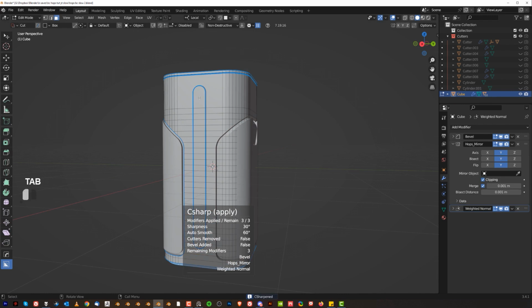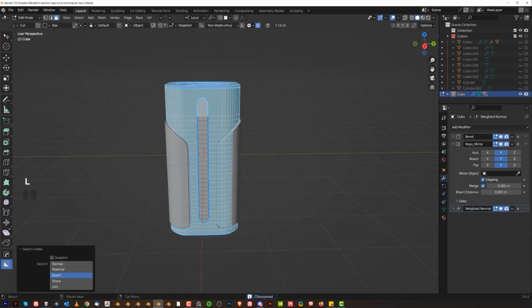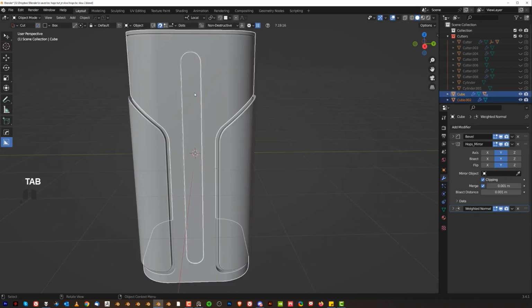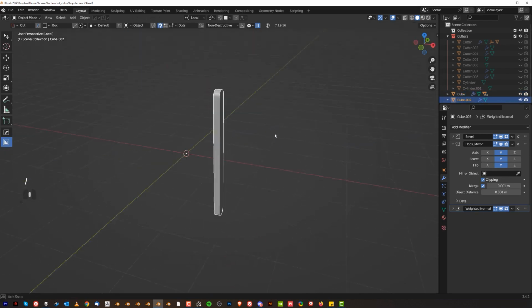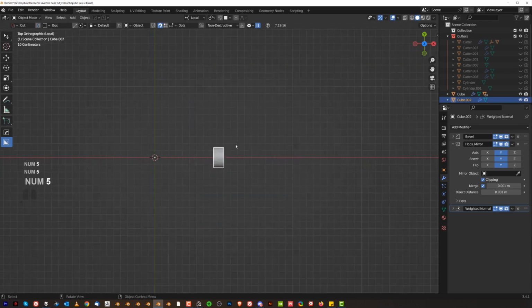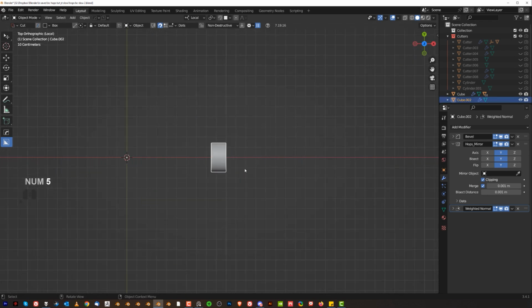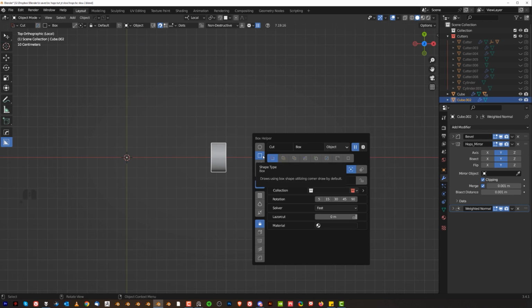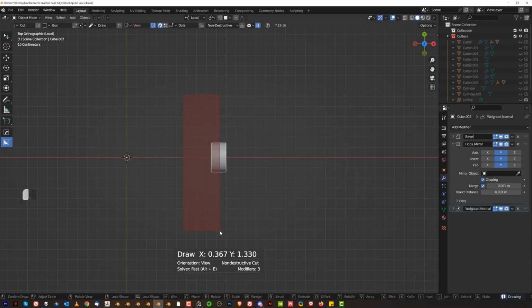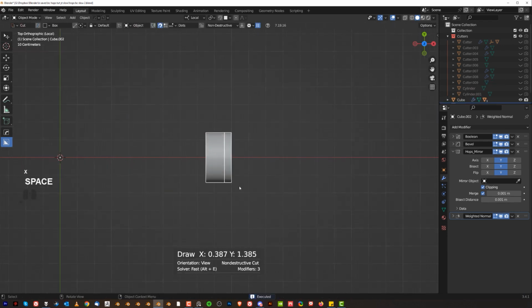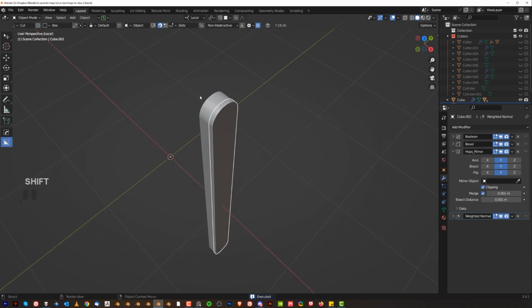I'm going to grab this face here and press L in the middle, and press P and selection. Now what I want to do with this is bring it here and split it. So watch, I'm going to click that D, select the square and cut it in here, press X and slice it, and I want to add the material to the top and the bottom.